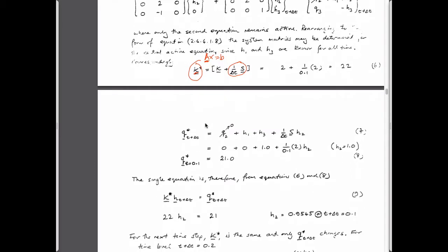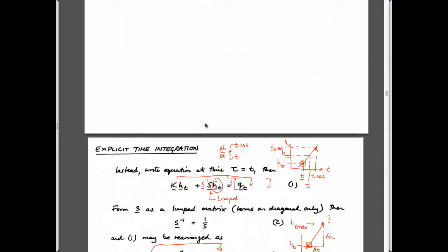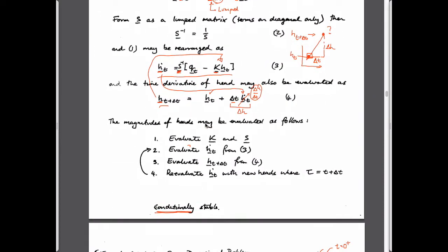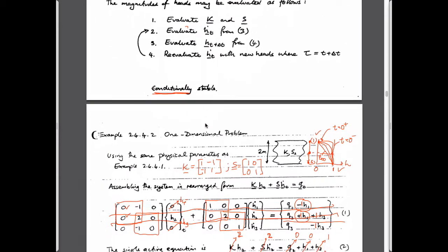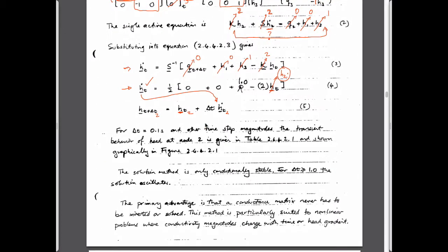So if you wanted to change the time step, you'd actually change this effective conductance matrix, which is part of AX equals B. That matrix would change as a function of your choice of time step. Now our time step doesn't have any bearing on the matrices that we use, and so it can be changed to accommodate maybe rapid desaturation or rapid changes in fluid pressures that occur for some reason or another. And so that's one of the advantages of using explicit methods rather than implicit.